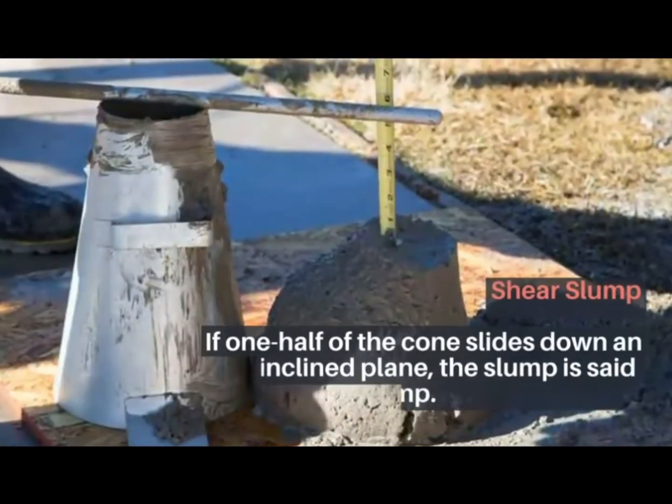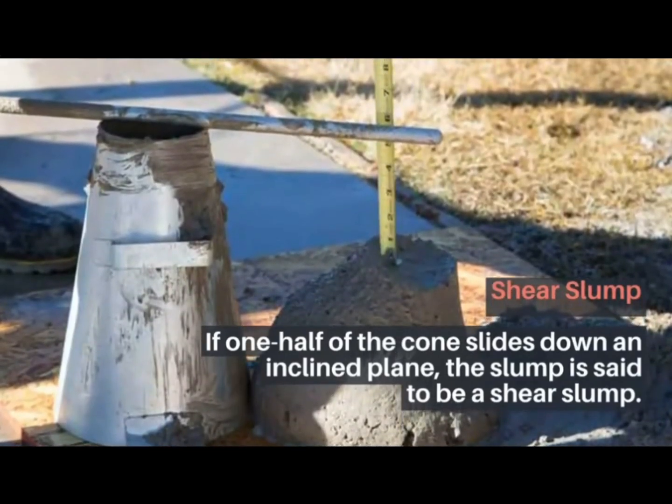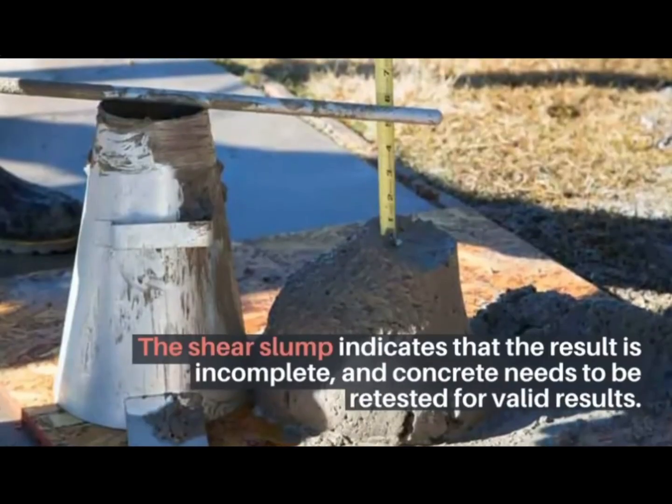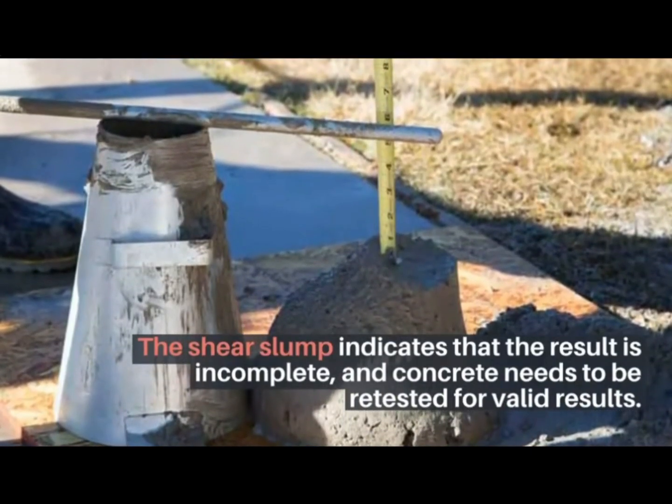Shear slump. If half of the cone slides down an inclined plane, the slump is said to be a shear slump. The shear slump indicates that the result is incomplete, and the concrete needs to be retested for valid results.